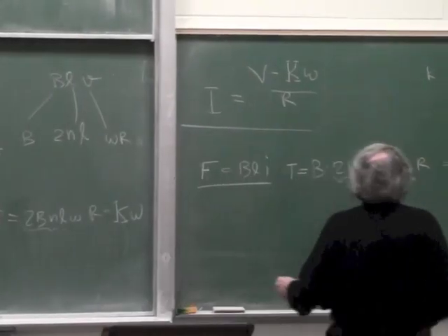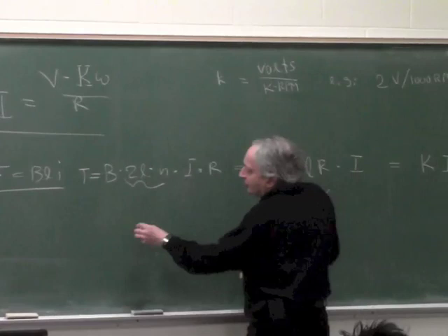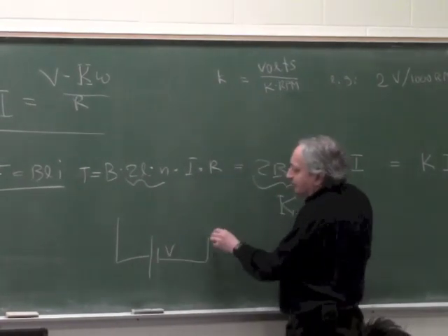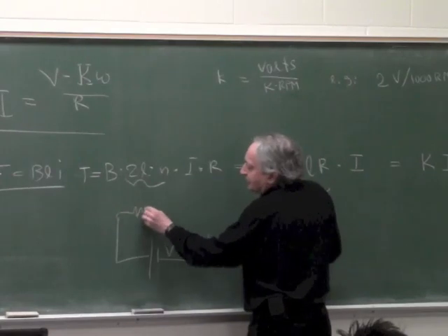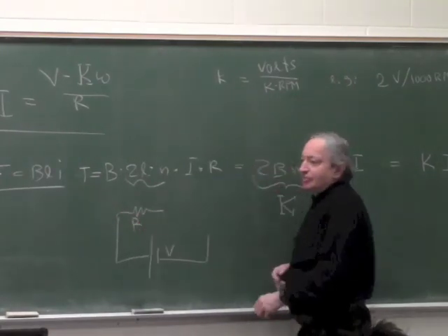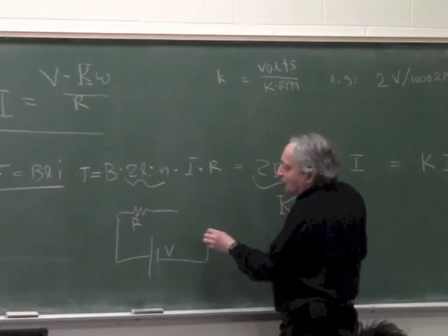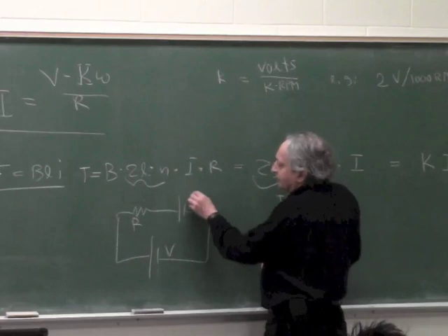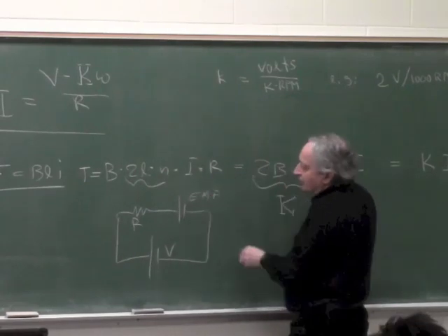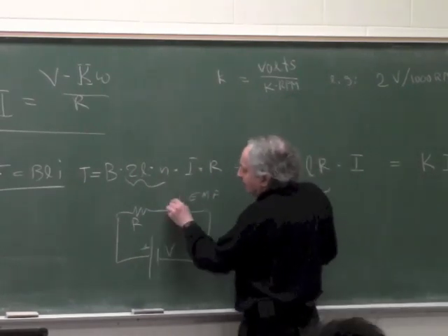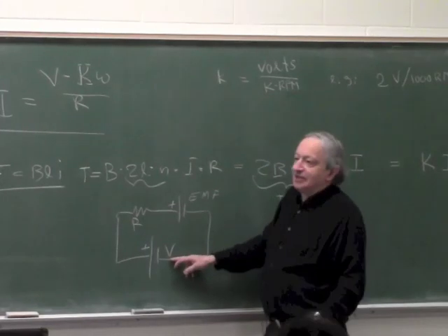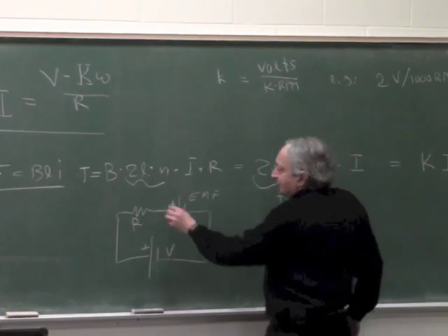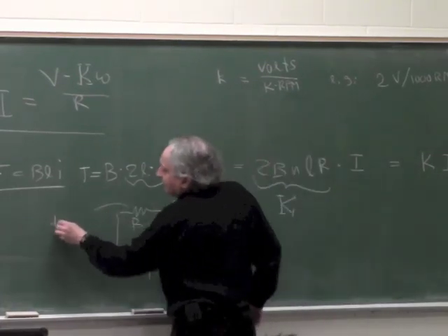So a better way to visualize it is we draw the electrical circuit. We have a battery V connecting to the motor. This is the internal resistance of the motor, and this is an opposing battery, which is a back EMF. So this is a back EMF, which is a voltage generated to oppose this battery, and it goes up with the speed.